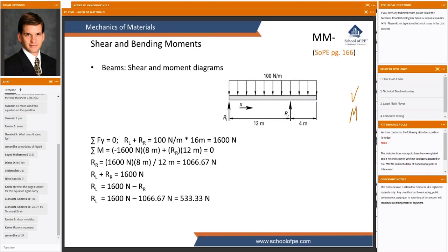We can then identify places where, for example, if we think there's a strong bending moment right there, then maybe we thoroughly analyze that particular location on the beam to try and figure out if it's in danger of failure. So we're trying to figure out where the maximum stresses are, and we're going to start by figuring out where the maximum shear and bending moment might be in a given shape. So looking at this diagram, our first task really is to find the reaction forces.